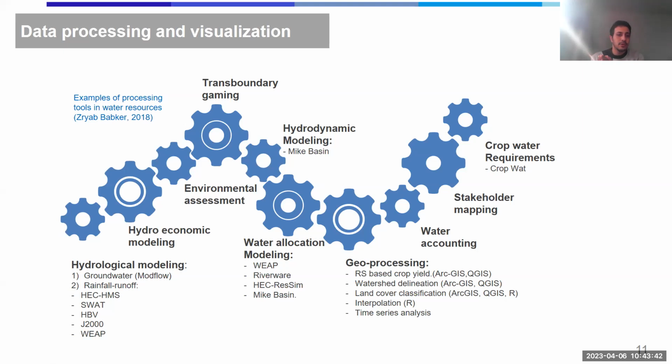From the digital elevation model, you can get the stream flow and the flow accumulation, and after some steps, at the end, you will run one function to give you the border of your catchment, which is the natural boundaries, as we mentioned before. These natural boundaries come from the elevation, and elevation shows us the stream flow. The catchment is surrounded by mountains or anything else, so any drop that enters this catchment will go to the middle. If it goes beyond this point, it will not go to this catchment, so this is not our border.